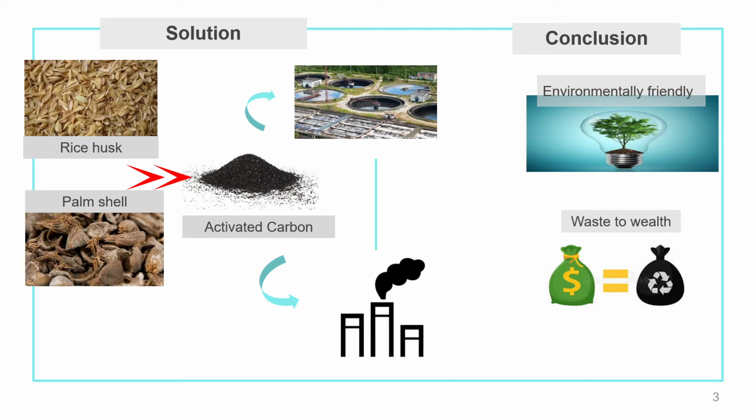How are you going to produce this activated carbon? There are two different processes for activated carbon preparation, which are physical and chemical treatment. Physical treatment involves two steps. First is carbonization and second is activation. It's a process which involves the reaction of the raw material with CO2, steam, or a mixture of gases and steam at high temperature reaching above 700 degrees Celsius.